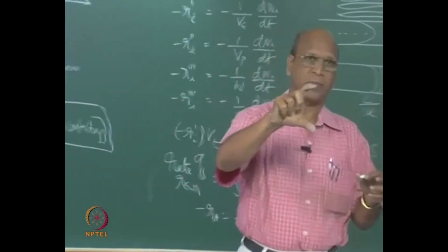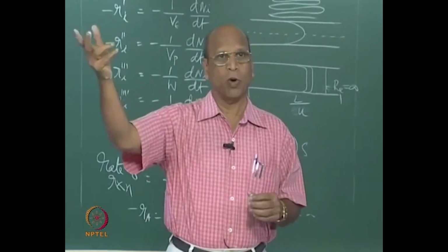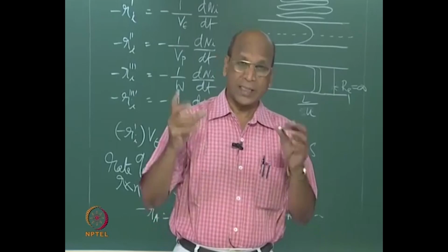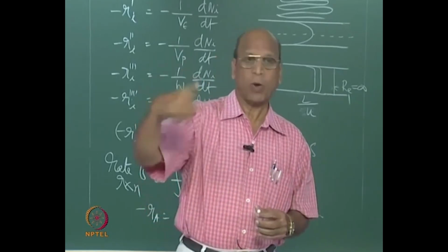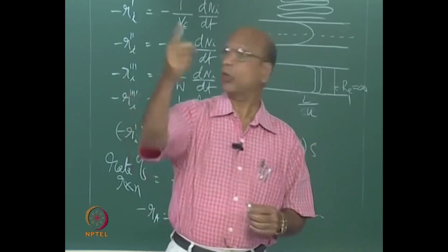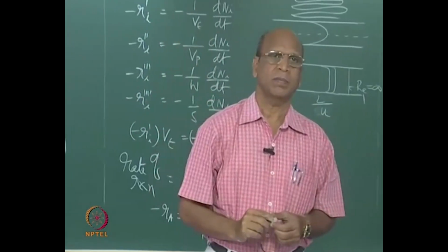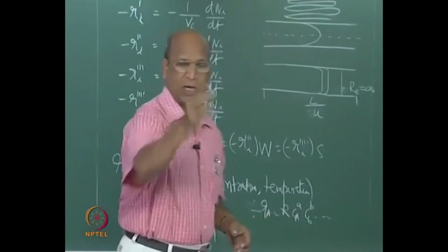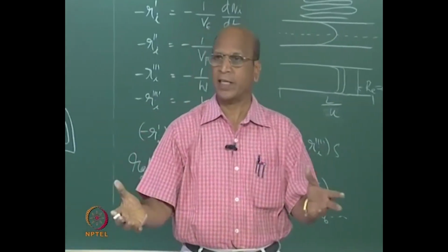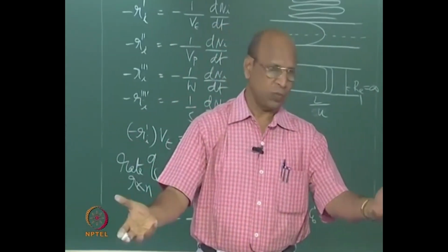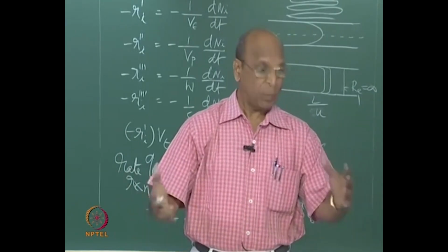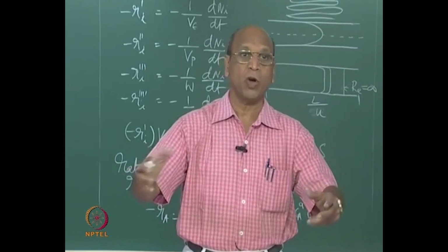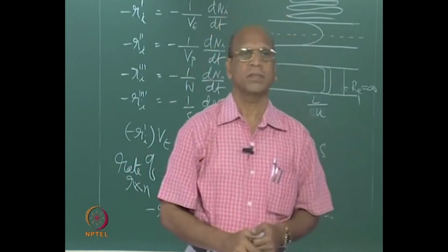So, that is fixed. Then when you are going for plug flow, the velocity required is very, very high. So, to provide that much residence time, the length will be very, very long. So, that is the reason we do not go. Okay. Her doubt is then why the same thing is happening in the mixed flow also, right? That is correct. What she asked is right. But here I have flexibility in increasing the diameter and also length.